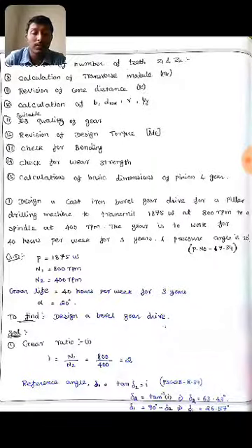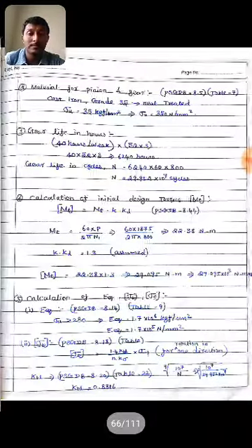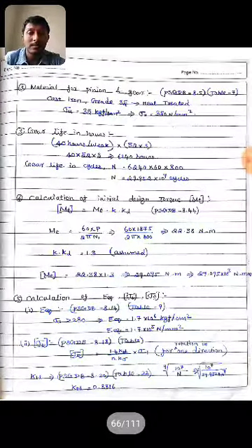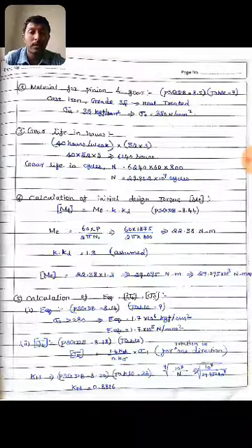Reference angle. So tan del 2 is equal to I, from the PSG data book page number 8.39. Del 2 is equal to tan inverse of I. Substitute the I value, find out the del 2 answer is 63.43 degree. Del 1 is equal to 90 degree minus del 2. So del 1 is equal to 26.57 degree.